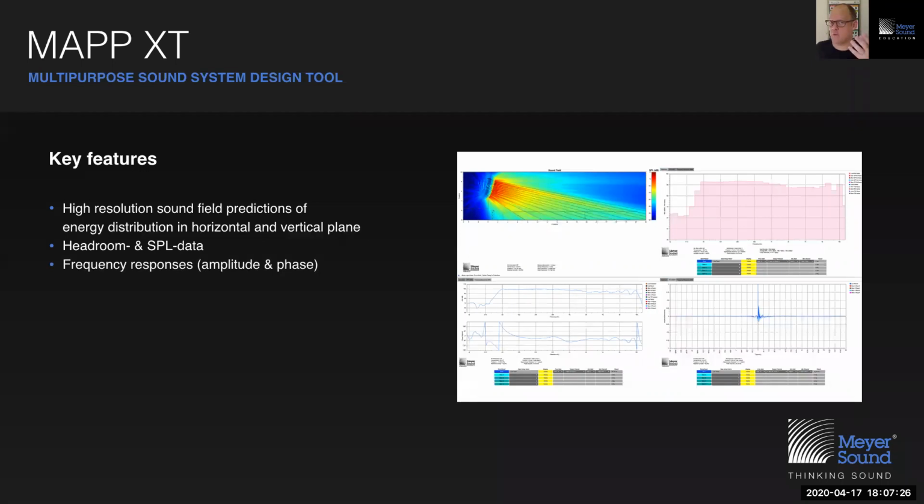It will show you frequency response, which consists of 2 parts. There's the so-called amplitude portion, the amplitude curve, or frequency response, also colloquially referred to as amplitude curve. And then there's the phase trace. And we show you both, and the phase trace is equally important, if not more important, and is the reason that Meyer Sound developed proprietary solutions such as delay integration, which is today part of product integration.